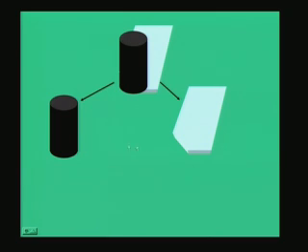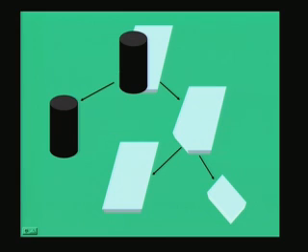The cylinder is easy to visualize. You can do a boundary representation of cylinders very easily using sweep. How to generate this particular structure for the rectangular parallelepiped? Well, I will say that this is also based on the combination of two different objects. I can take a rectangular parallelepiped and then subtract a small portion of that with another small object. So, if you see the large object on the left hand side, that is object A, and the right hand side has object B, then the object here, which is this rectangular parallelepiped with a broken part, can be obtained by taking the operation A minus B.